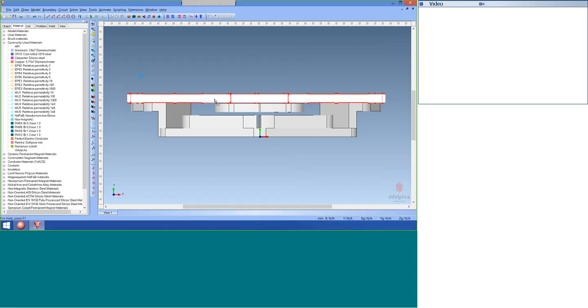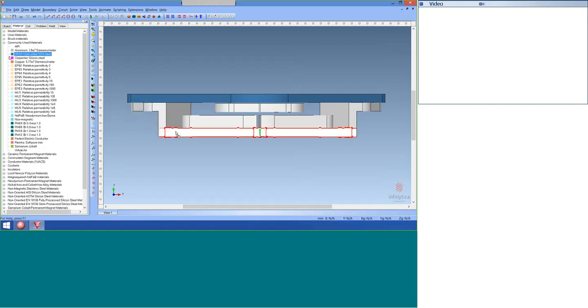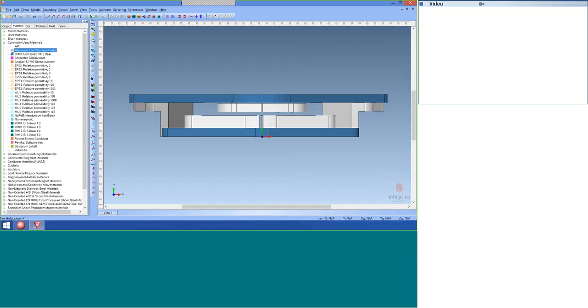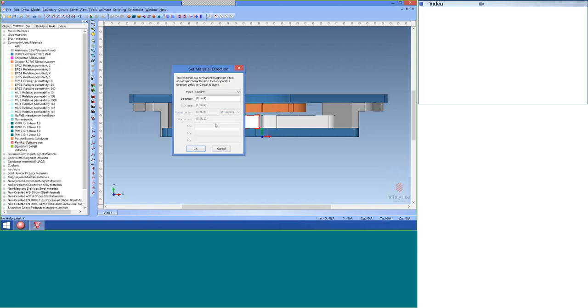generic. We'll make the top plate and the bottom plate here out of cold rolled steel. We'll also assign aluminum to the side brackets. The coil is just part of the top here, so we'll make that out of copper. So we'll choose copper from the list here. The coil is actually set up in two parts here, so that we have internal faces to assign coil windings to. And the last part for this voice coil motor is to assign permanent magnet materials.